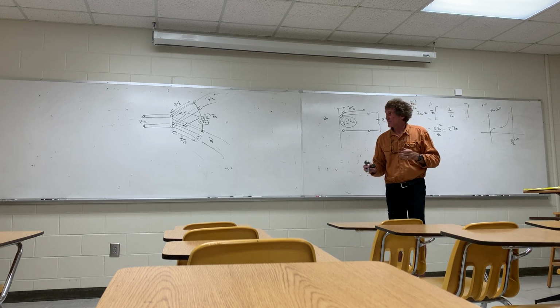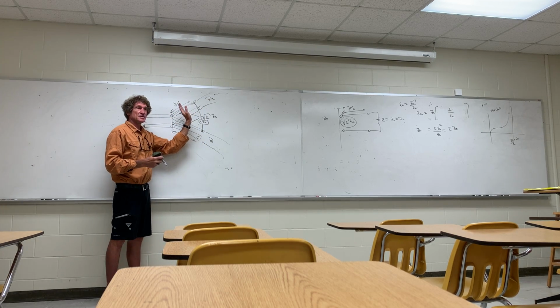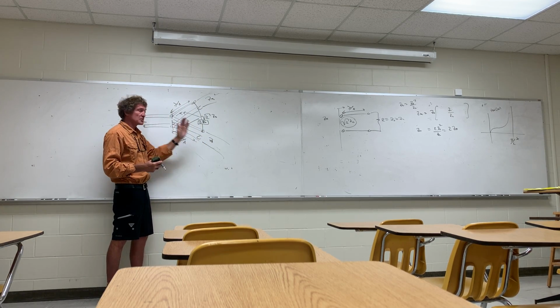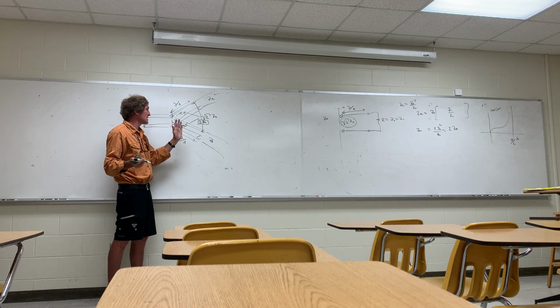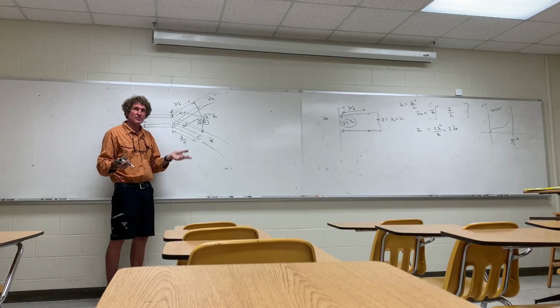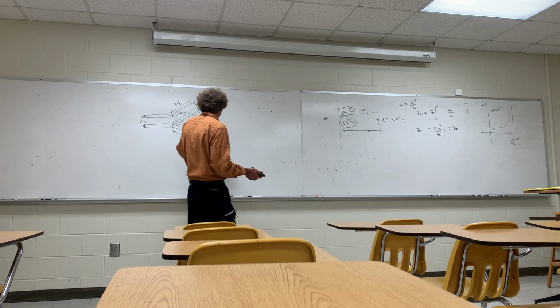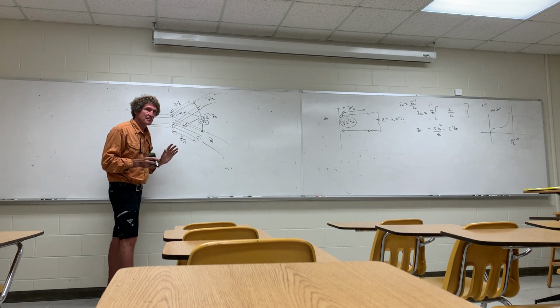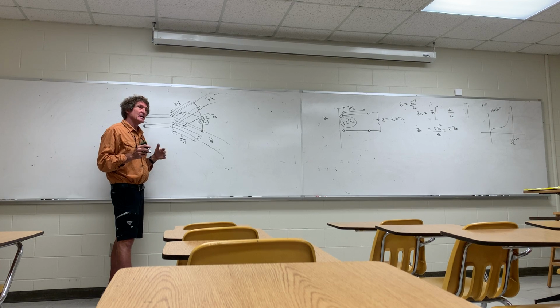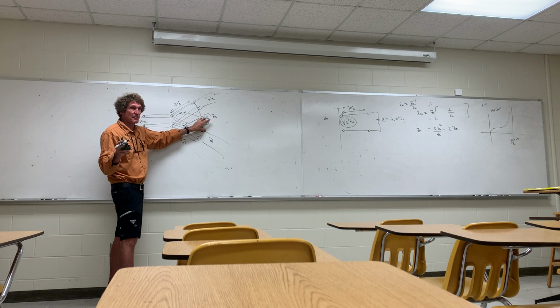All right, 2 Z naught right here, if I look at this point, and I look at this transmission line, it's 2 Z naught, this transmission line, 2 Z naught, they're in parallel, it's exactly Z naught, which means the impedance I'm looking into is the same as where I'm coming from, where the reflection coefficient is 0. Now, this resistor in there, ideally you don't need it, all right? The reason is because you get imperfections, non-ideal things, and if you don't have that resistor there, then you can get all sorts of weird standing wave things that can happen. I can only tell you that much about it.